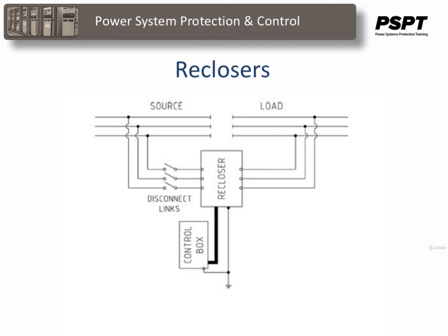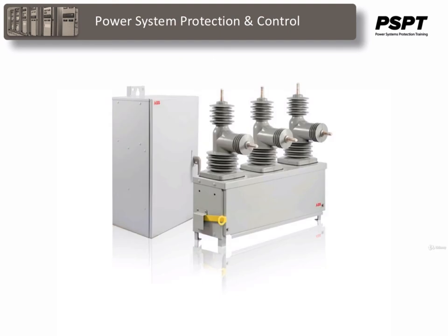If a recloser goes through only part of its cycle, short of the lockout, it resets itself automatically within 1 to 1.5 minutes. A locked out recloser must be reclosed manually, and it is usually located immediately off the secondary circuits of the distribution station transformer.